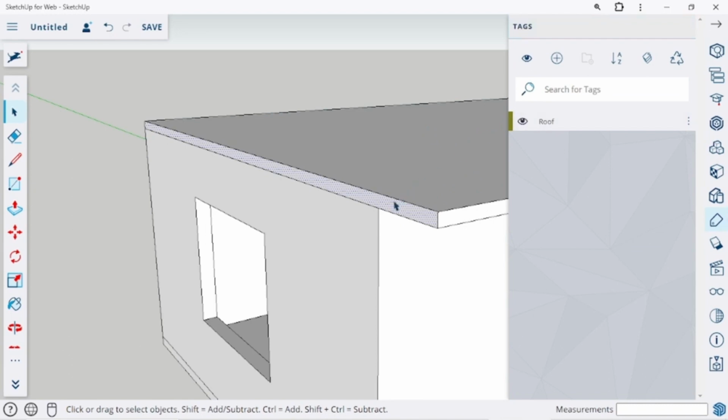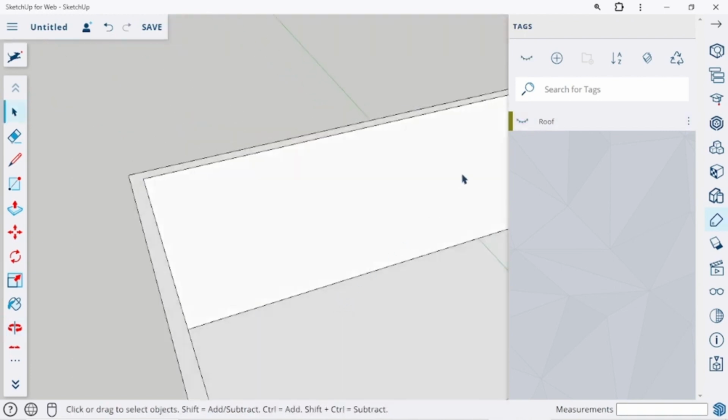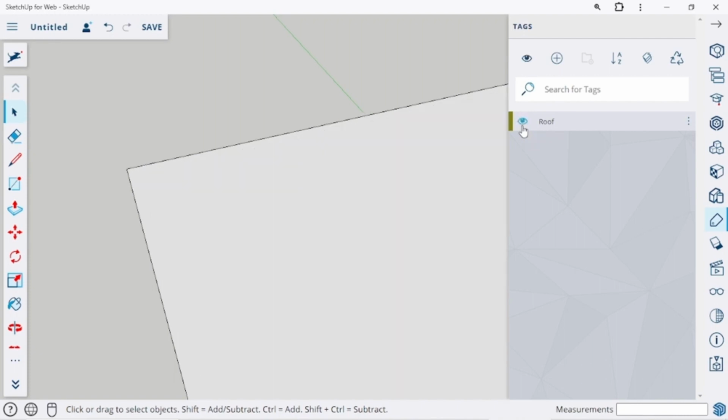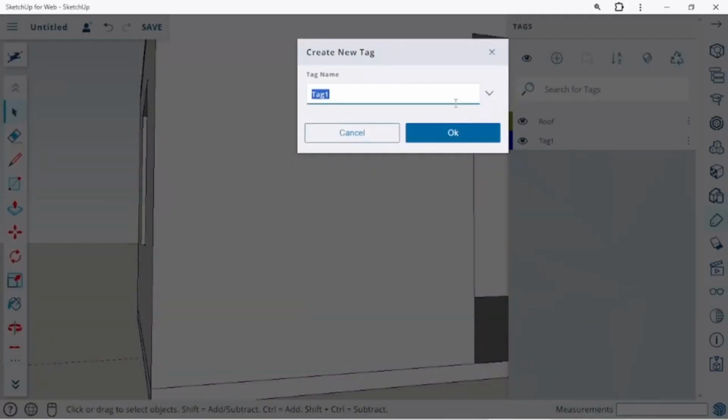Now, the reason why the tag is important is that, let's say I want to place an object inside this building, I could turn this off and then automatically the roof disappears. Not that it's been deleted, sorry, its attribute has been hidden. So once I click back, it displays, and so that's the use of the tag. So our next is walls.